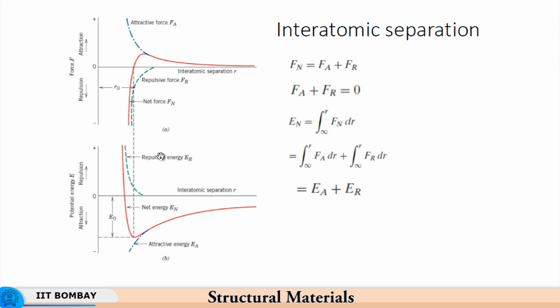Anything more than that, it will tend to go away from its stable position where 0 force was acting. So it will get pulled in the direction of the force, and when the force is released it will come back to its original position. If the atom is pulled this way, it will get deformed because you have supplied some energy using a certain force, but if you remove the force, the atom will come back to its original position because it will achieve its minimum energy level at 0 force. So this leads to what is called elastic deformation.